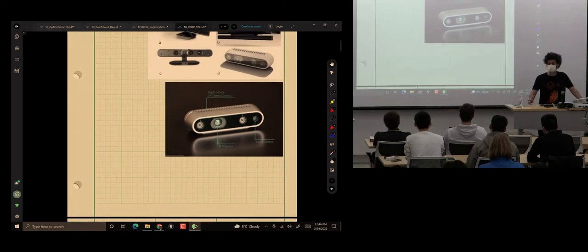And you see it on a lot of robots these days. They use this camera because it's small, it's relatively cheap, and works well. Although it's good for indoor, if you use it for outdoor, you can solve the problem for short range, 5 to 10 meters, but the point cloud will become noisy, as we will see the brightness constancy assumption will be violated. We'll talk about it.